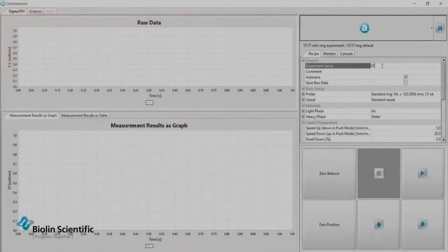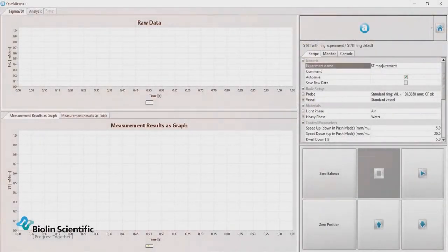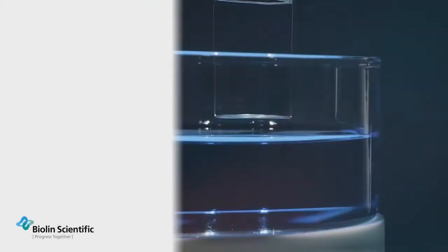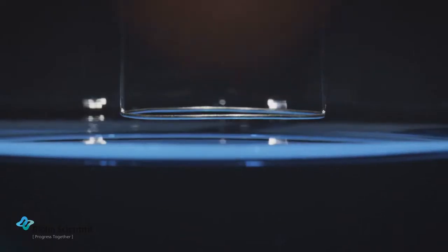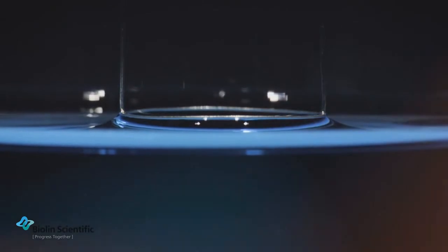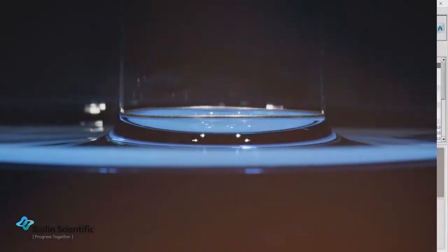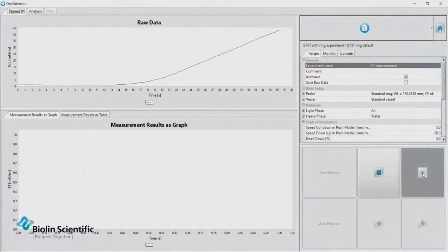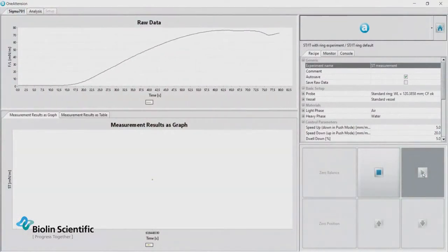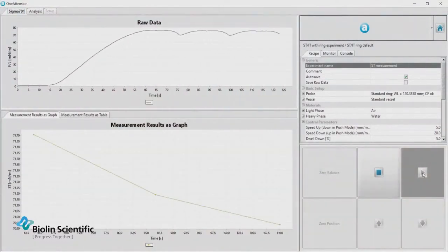The Tension Sigma 700 and 701 measure the surface tension and the interfacial tension of a liquid by measuring the force the liquid places on a platinum probe. The fully automated measurement starts by the probe being immersed in the studied liquid. The system automatically detects the surface position, and after wetting, the probe starts approaching the surface gently with the help of an extremely precise lift.